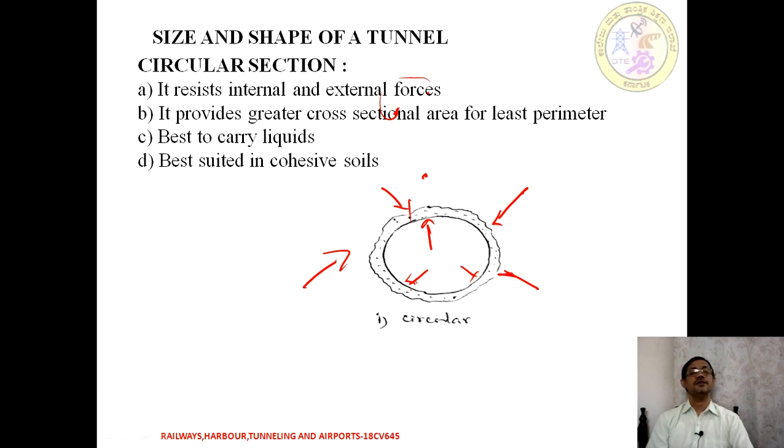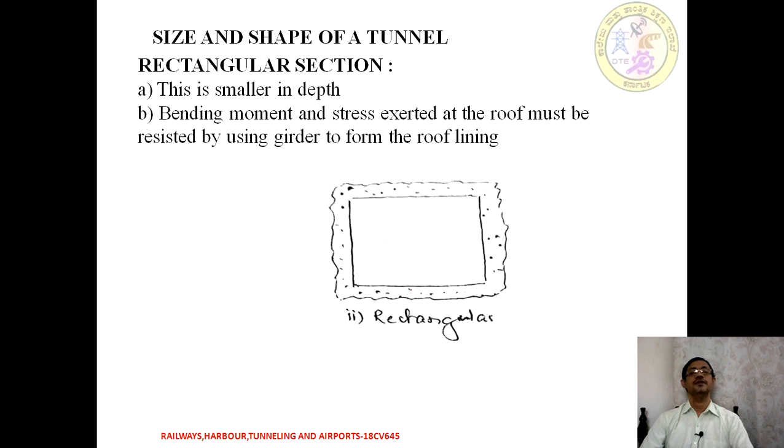So it provides a greater cross sectional area for a least perimeter. As far as the geometry is concerned, it is best suited to carry liquid, and it is also best suited for construction in cohesive soils.